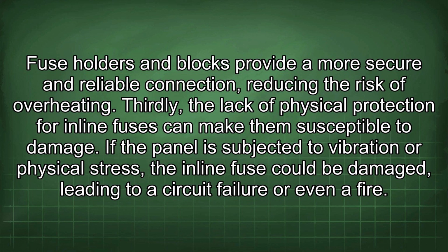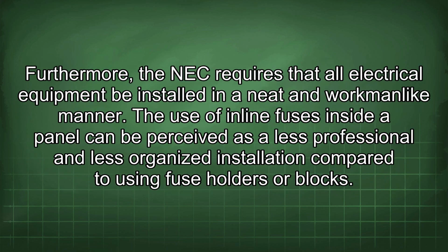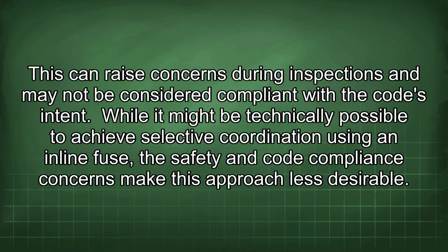Thirdly, the lack of physical protection for inline fuses can make them susceptible to damage. If the panel is subjected to vibration or physical stress, the inline fuse could be damaged, leading to a circuit failure or even a fire. Furthermore, the NEC requires that all electrical equipment be installed in a neat and workmanlike manner. The use of inline fuses inside a panel can be perceived as a less professional and less organized installation compared to using fuse holders or blocks. This can raise concerns during inspections and may not be considered compliant with the code's intent.